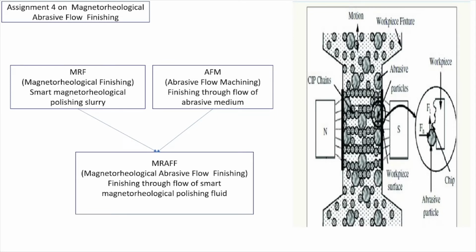We know about Bingham plastic polishing fluid, which acts rigid at lower stress and, at higher stress, acts as a fluid. This behavior follows that the shearing of the Bingham plastic polishing fluid near the workpiece surface contributes to material removal. So in this process, whatever material removal and finishing takes place is because of the shearing of the Bingham plastic polishing fluid, near the workpiece surface region.